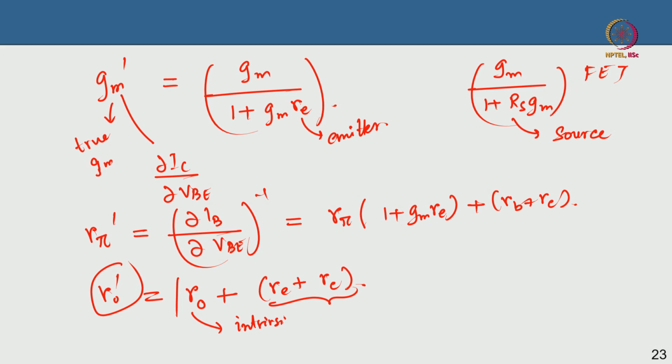The device capacitance components are still the same because C mu and C pi will remain the same. They depend on the expressions that I wrote down earlier, they will just be the same. So this is basically the small signal model in which the extrinsic resistance is considered.